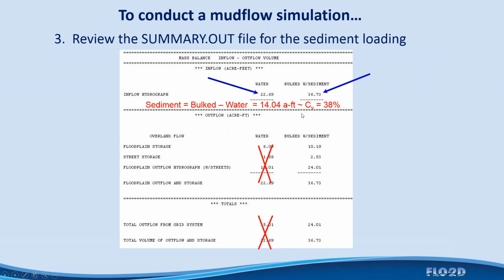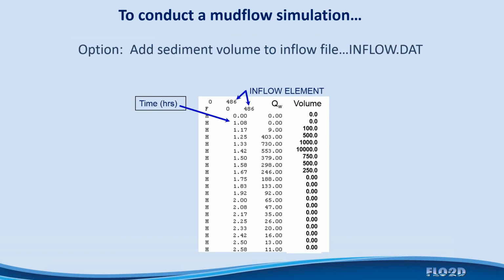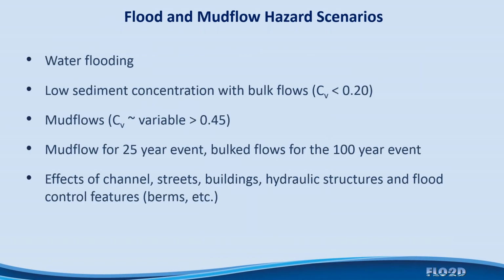and you'll do it the same way. When you run it, you'll subtract these two values and this will be the total for you, and that should be equal to the 5 foot of depth times 100 foot width times 500 foot length, and adjust for the porosity because this is a solid volume here. So you want to make sure you do the ground to solid volume adjustment factor, which is porosity of 40%.